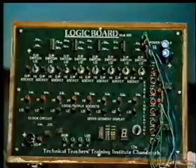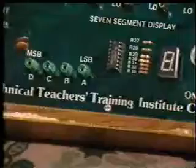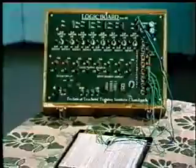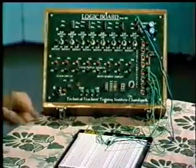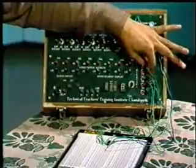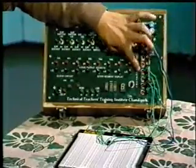There are circuits like digital counters where the decimal equivalent of the binary output of the test circuit is required to be observed. For that, a decoder with 7-segment display is provided on the logic board. 4 outputs of such a test circuit are fed to the 4 test sockets. The LEDs show that the output is 1, 0, 0, 1.